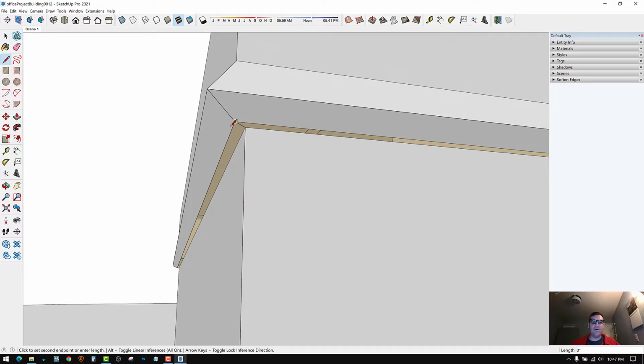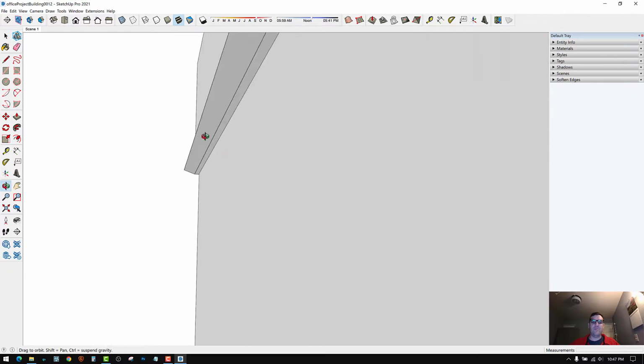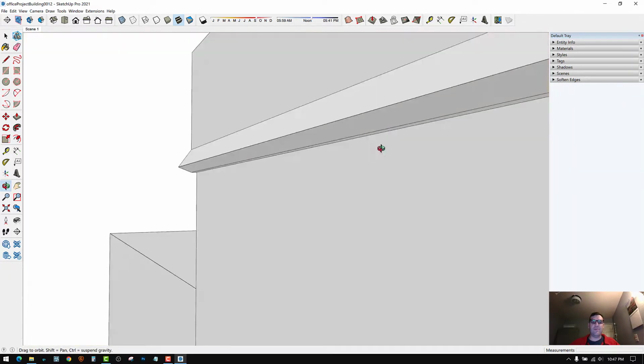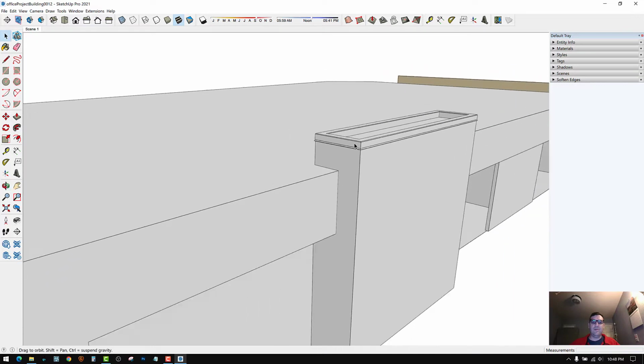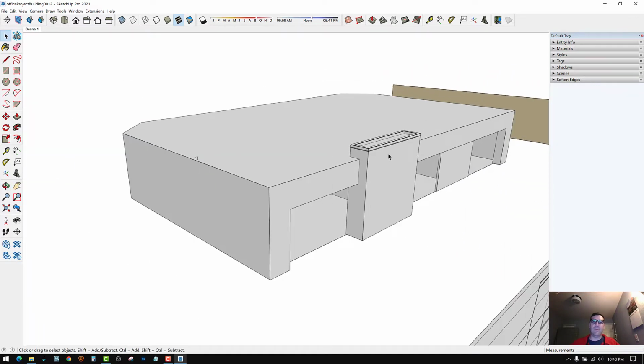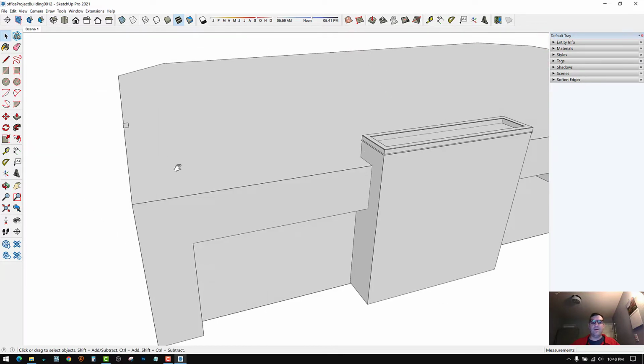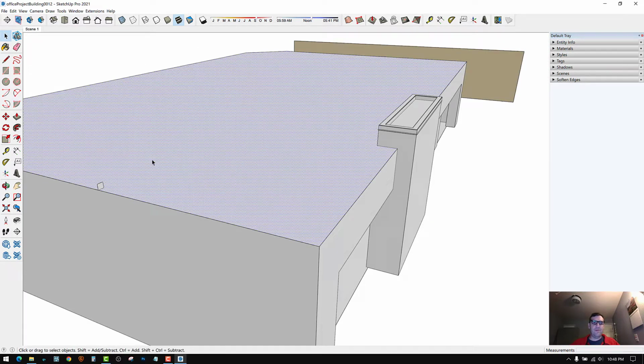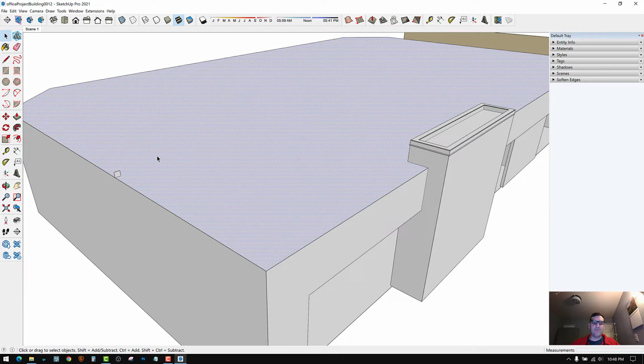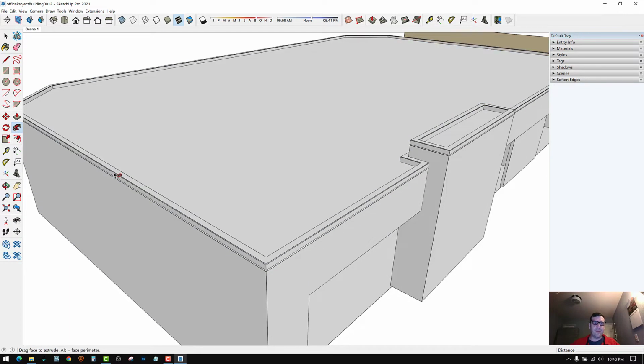So I'm going to have to redraw a couple lines until it shows back up for us, because we don't want to have holes in our model. Yeah, that looks good. And then someday if we want to 3D print this model, you can't 3D print it with holes in it. So let's try it with this one too. Left click on the edge face, and then click follow me tool, click on the profile.